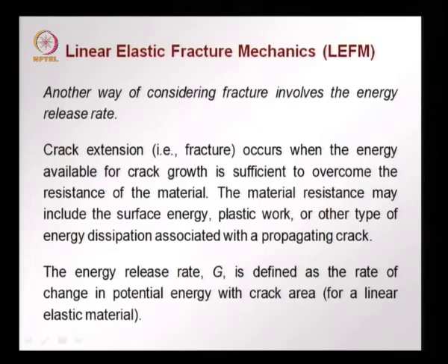This energy should be sufficient to overcome whatever resistance that comes from the material itself, and this material resistance can come from the new surface energy that is going to be created, plastic work or the work that goes into the yielding, and any other type of energy dissipation like heating, noise and so on. All that is some form of energy that accompanies a crack.